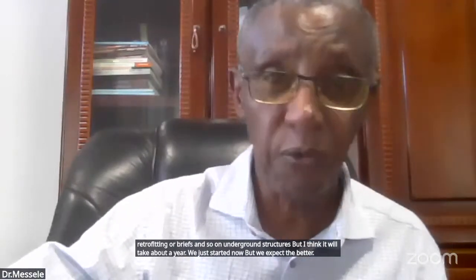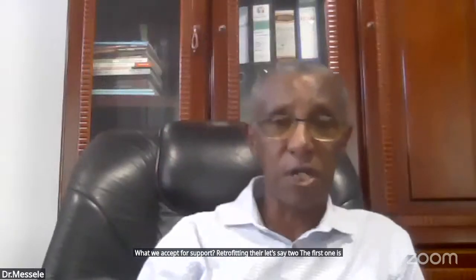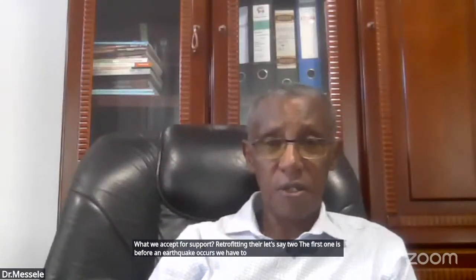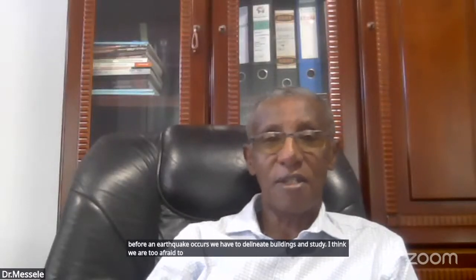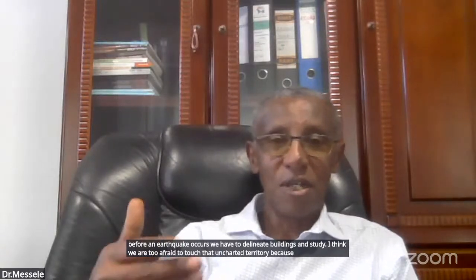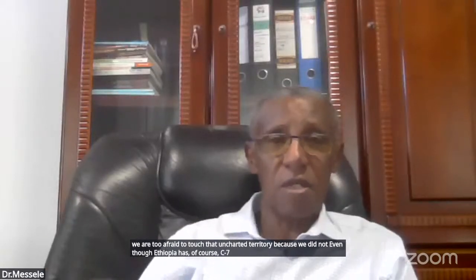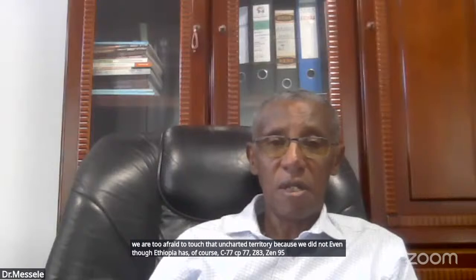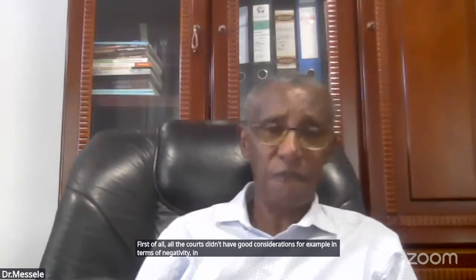What do we do, except for the code, about retrofitting? There are, let's say, two conditions. The first one is before an earthquake occurs: we have to delineate buildings and study them. I think we are too afraid to touch that uncharted territory. Ethiopia has had codes since 77, then 83, then 95, many years. But the old codes didn't have good considerations, for example in terms of ductility, even stiffness, or detailing. They said nothing.